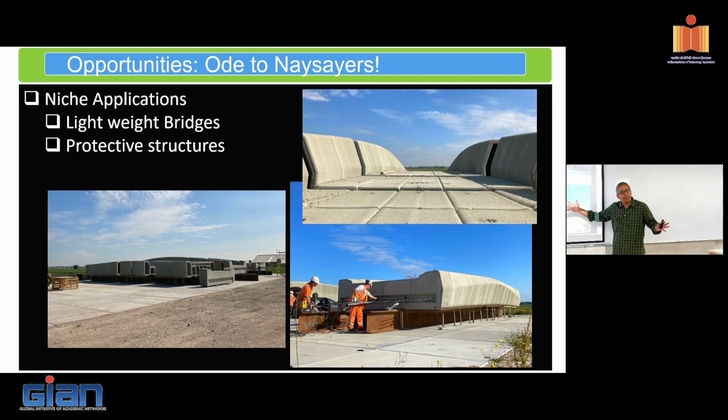Here, what you're doing is you're compressing it. And the beautiful thing here, and I'll play up on this concept a bit more, is I'm using a self-equilibrated system. Here, concrete is in compression, steel is in tension. So basically, both of them are nicely self-equilibrated, right? That's what typical PT structures are all about. And I'm playing off the strengths of both materials. Steel takes tension, strong in tension. Concrete, compression, strong in compression. So I'm taking advantage of where the two materials perform the best.